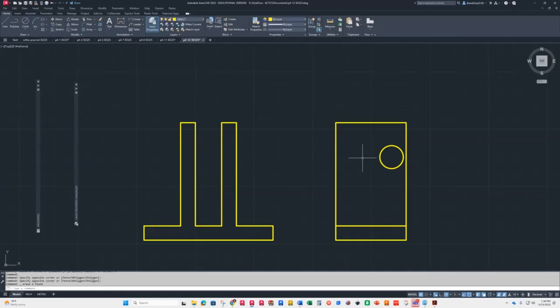Okay, so the book is missing a line for the top of the chamfer there on the one, which would be the chamfer right here. Actually, it's the top line that's missing. So I need to put a 45-degree angle chamfer right here. You'll notice the next one up says 4x space 0.50 space x space 0.50. Why am I doing it like that?